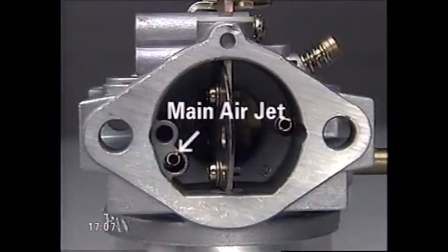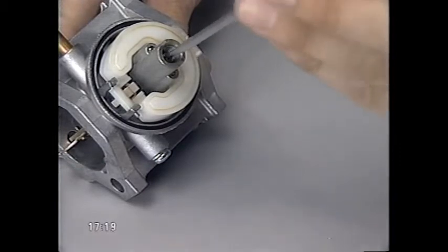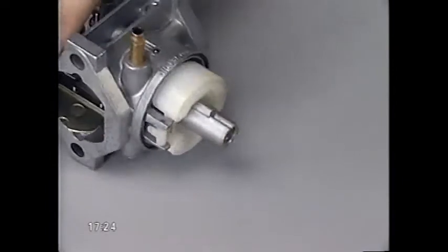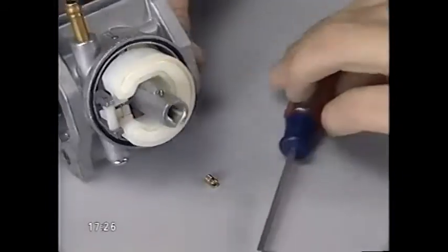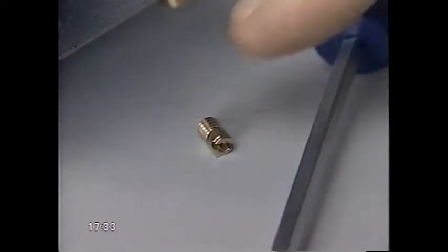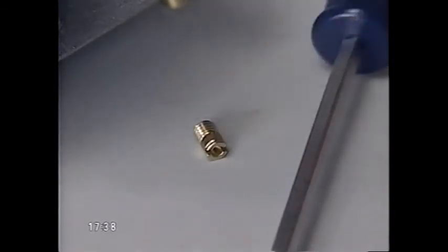The main air jet is built into the wall of the carburetor, and no adjustment can be made to it. Some, however, are replaceable. The main fuel jet cannot be adjusted either, but it can be removed from the nozzle tube for cleaning or replacement. The size of the orifice in the main jet is determined by the engine and its application. For example, if the engine will be operating in a high-altitude location, it may be necessary to change the jet to a smaller size for more efficient operation. Calibrated jets are available for altitude adjustment.